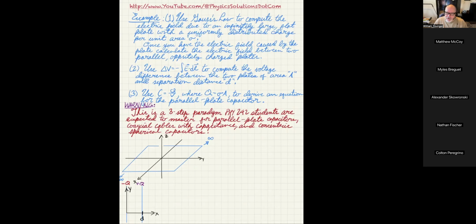that's in series, say, with the capacitor. If you then calculate R times C, that value, and you should check this unit-wise, comes out to be units of seconds. And it's the number of seconds required for the charge of a capacitor to go up by a factor of e, basically 2.71828. Or if you're discharging it, it's to go down by a factor of 1 over e.